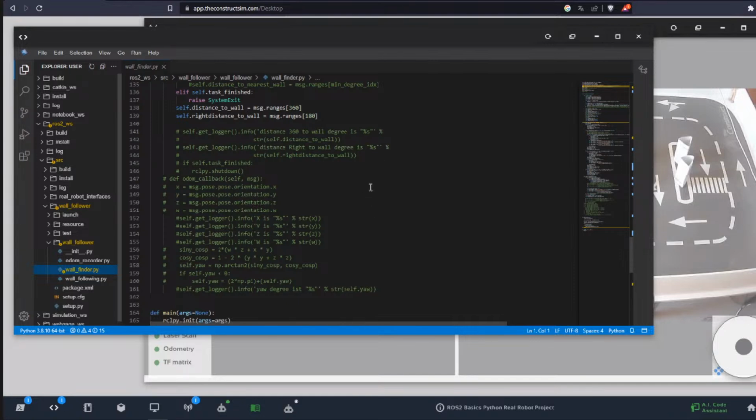Well, you also have this XYZW. That's a quaternion, it's not an Euler angle, and I can't really understand how quaternions are showing. But something you can do for this, another way of testing it, which is probably what I'm going to do, is connect to the robot and open RViz, and you can add the odometry to RViz as a topic.